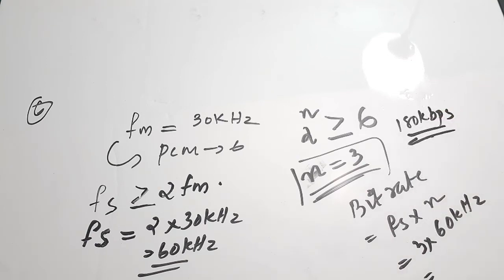While discussing a PCM question, you have to keep two things in mind. One is the sampling stage, second is the quantizing stage. In the sampling stage, you have to think about the sampling frequency, and while selecting the sampling rate, you have to keep Nyquist criteria in mind. Next thing is to find the number of bits with which each sample is getting digitized.